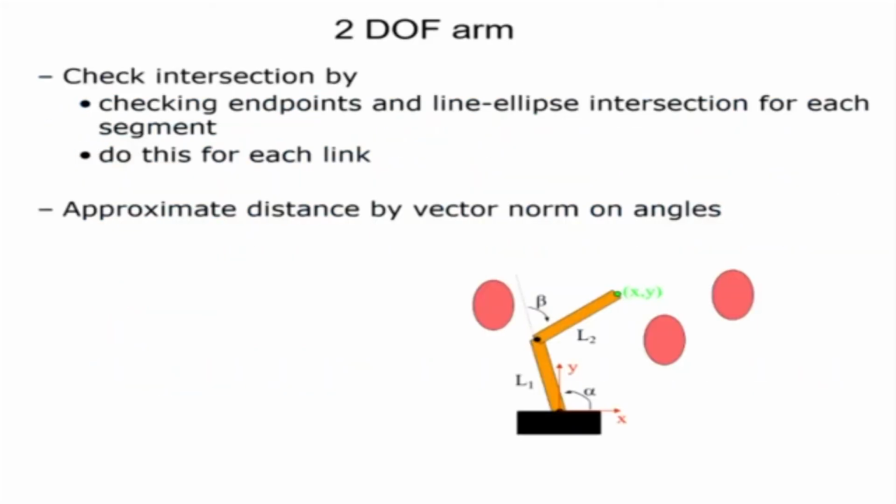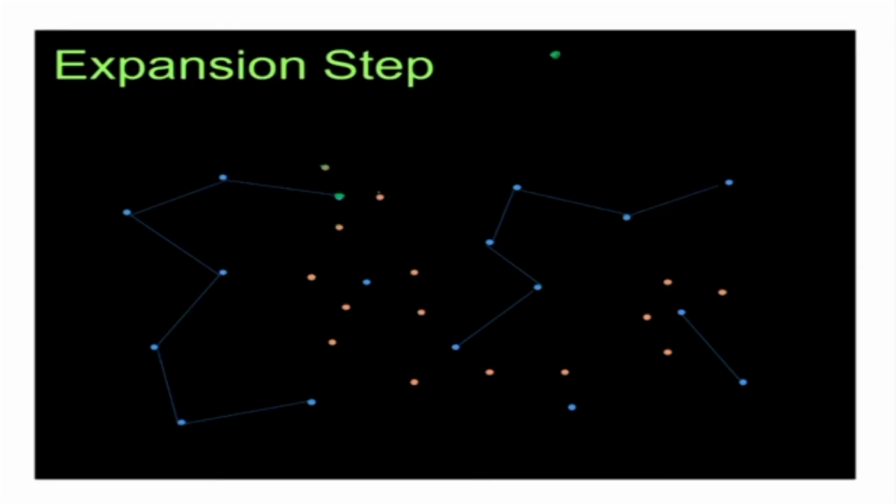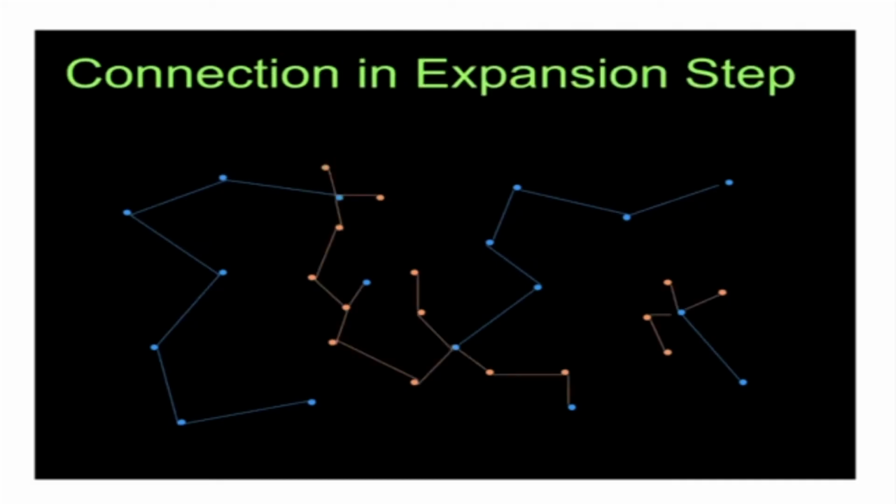What it means is that here you start with a random direction from C and go until you hit an obstacle. Now if you do not hit an obstacle, that means this is a possible path. So you add this to your edge and node graph and proceed like that. Now we will see that there can be different ways by which these branches can shoot off. But this is the basic idea of how we make the connections in the network of paths.